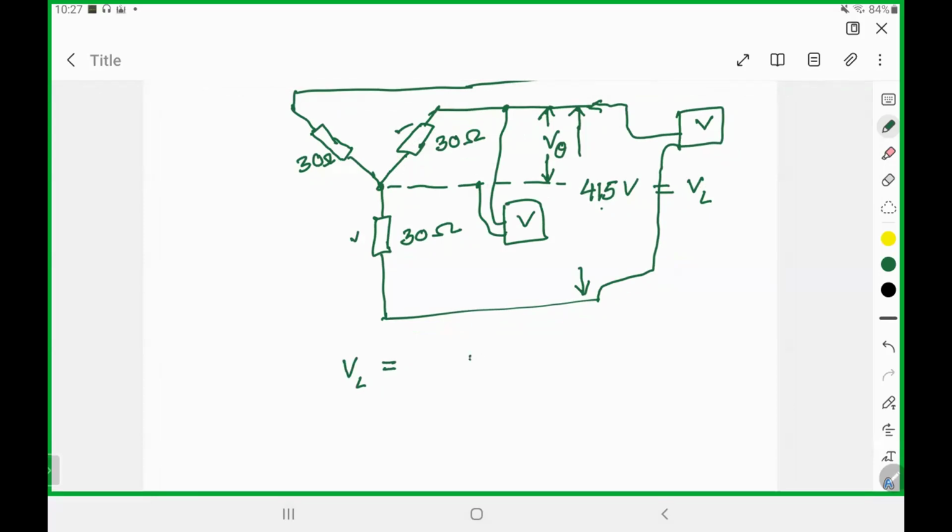So we know that this relation is given by a factor of square root of 3. So square root of 3, that means the line voltage is larger. That means if you multiply the phase voltage by square root of 3, then you will get the line voltage. Any line quantity, this is the beauty, so you don't need to memorize these things.